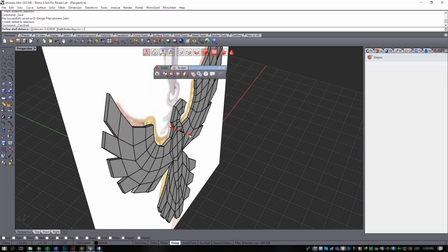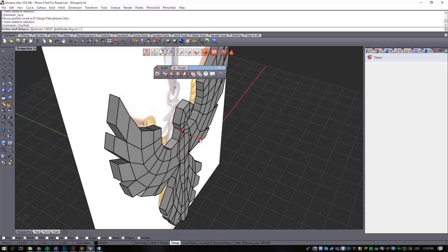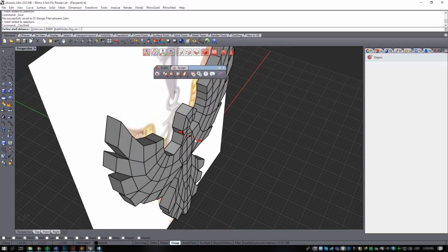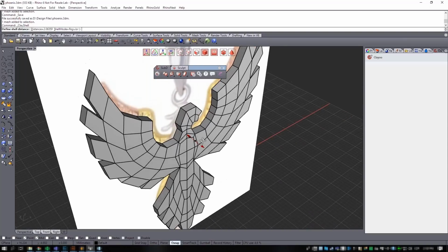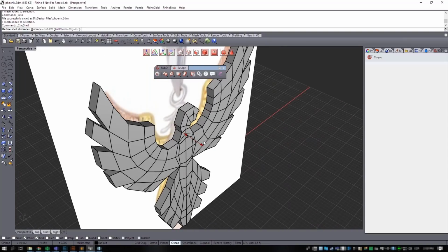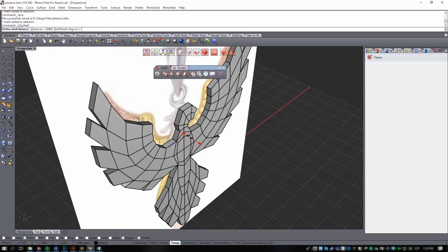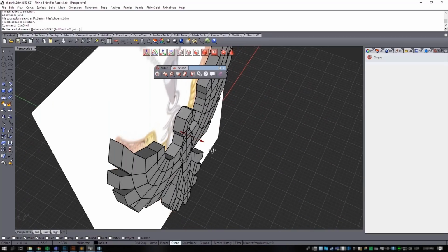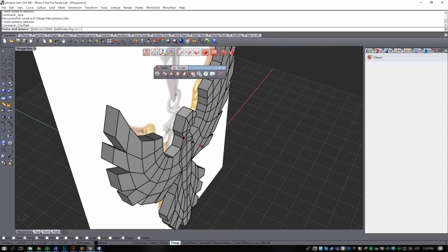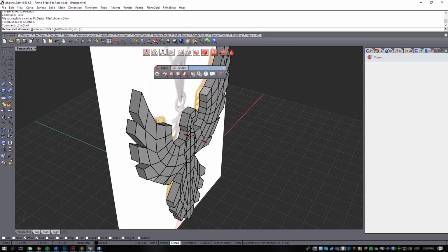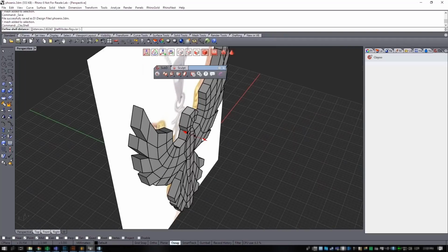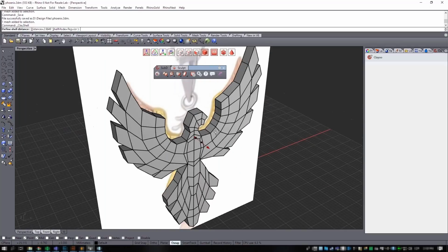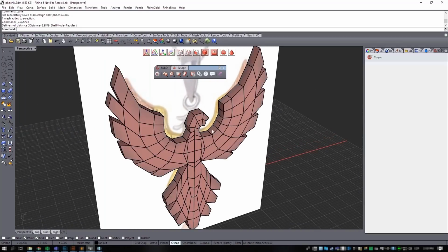So right now there's going to be an arrow here, so I can increase or decrease the size. It's the extrusion size, like the thickness. I'd rather have a small thickness here, maybe something medium, something like that. And then I'm going to use the external loop of faces just to make it a little bit smaller. Okay, something like that is going to be good. And just right click to validate.